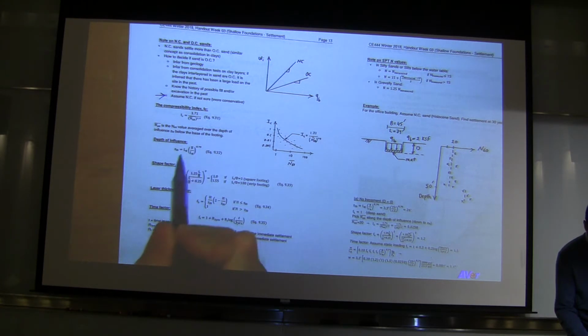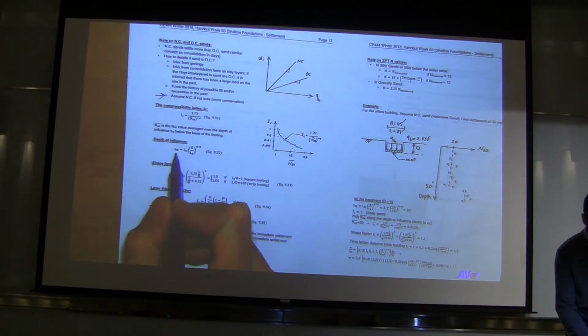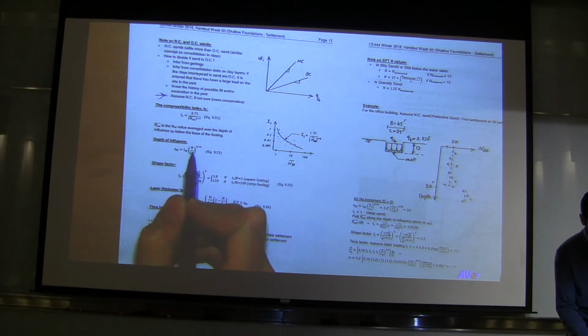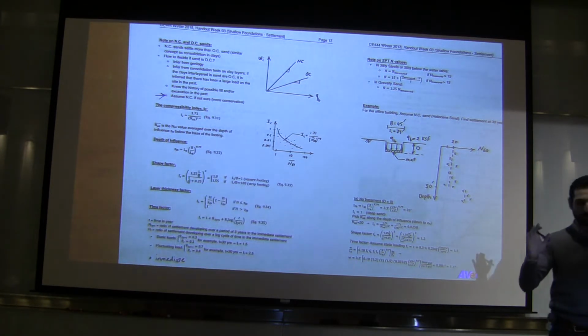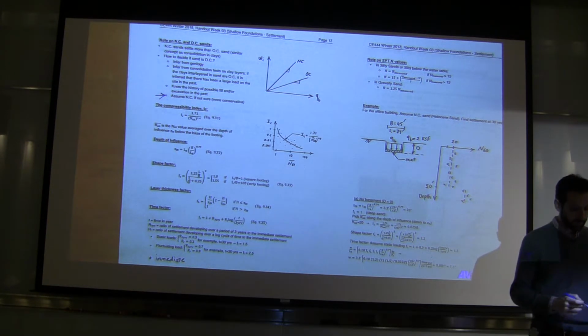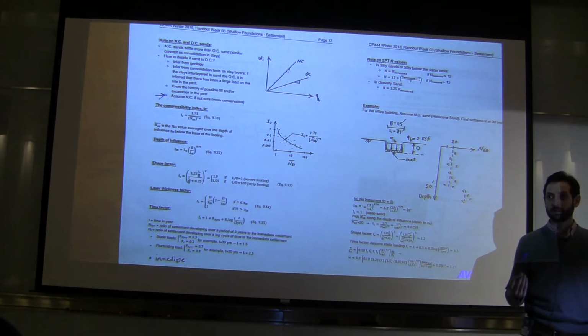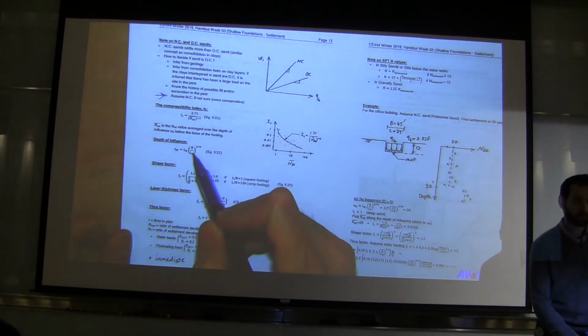So if you get rid of the LR, which is the unit conversion parameter, the depth of influence is basically equal to B to the power of 0.79. And forget about the 0.79, it's almost basically Z_f, or depth of influence, is almost equal to 1 foundation width, or 1B.